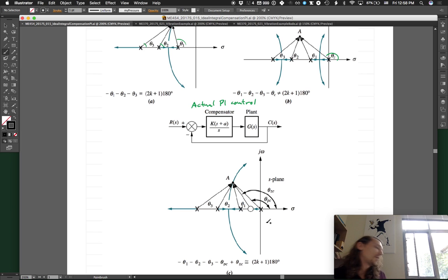You have to come up with a balance that you're comfortable with as a designer for the criteria that you want. So you might affect your transient response too much with a given 0 location, and so you might need to adjust it, but then you might end up with too slow of a response. So you've got to deal with the trade-offs that could come with this.